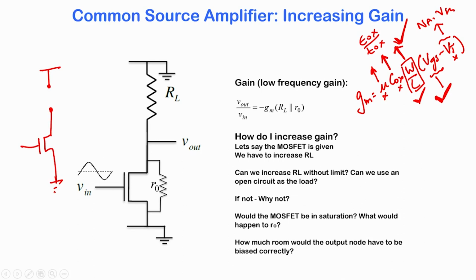Okay. So, this is going to be my amplifier circuit. So, I have my V in here, I have my V out there. Does it mean that I am going to have very high gain? Can I use this equation and say that RL is infinite, and Ro limits everything, infinite in parallel with Ro is basically Ro, and therefore my gain is very large? Can we say that?